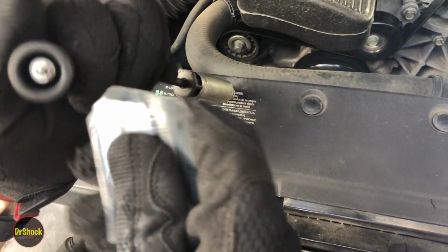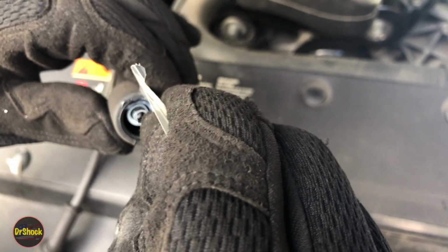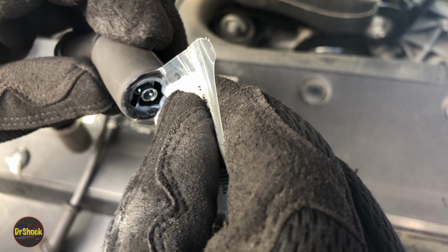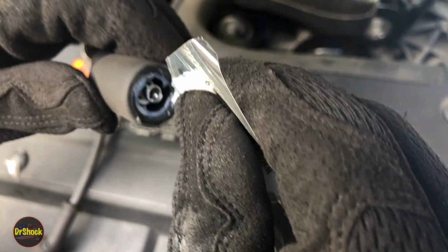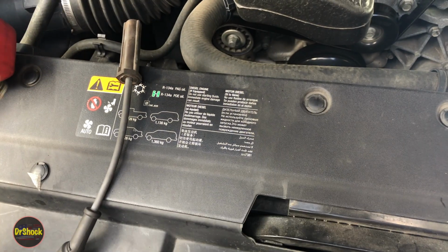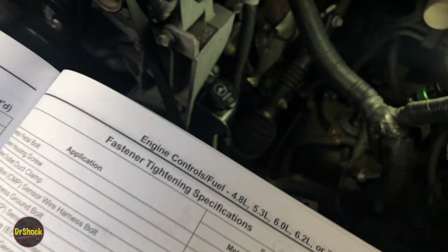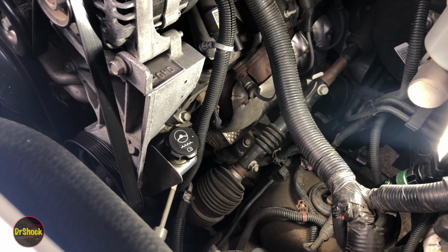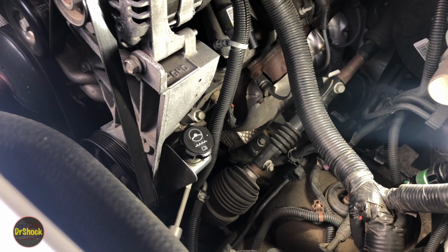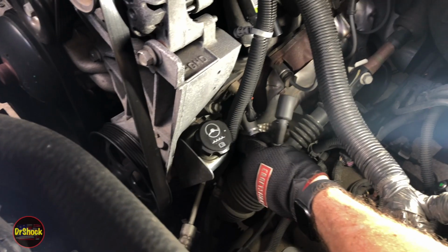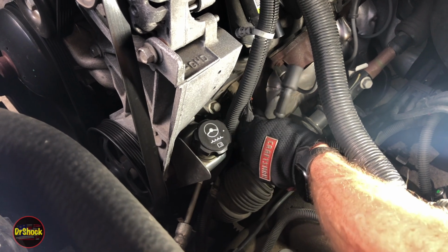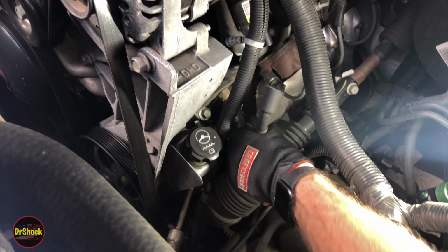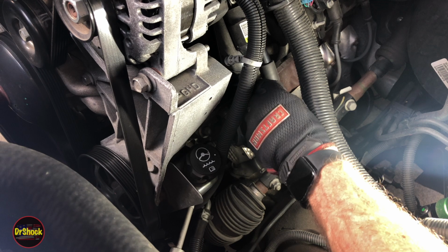And similarly, when we plug it into the coil, we just want a little bit around the outside. We don't want to get this on the electrical connector itself. We just want to smear it along the coil nipple. And you can also just put it on there manually to that same degree if you'd like. Gotta have a stool to get up here and see this guy. Always want to feel that tactile click, and you want to hear that click.